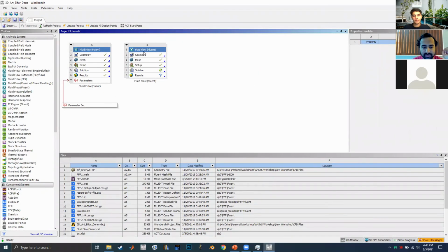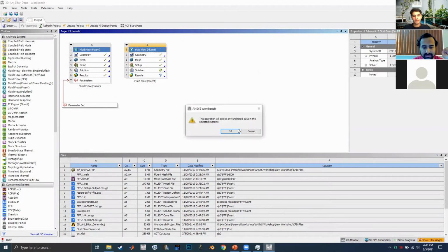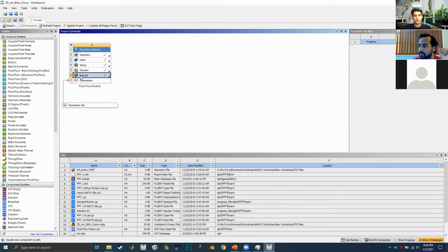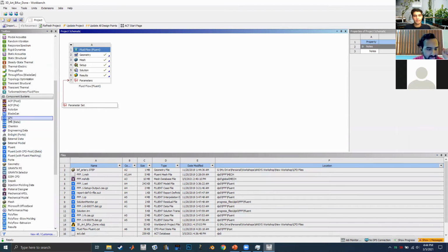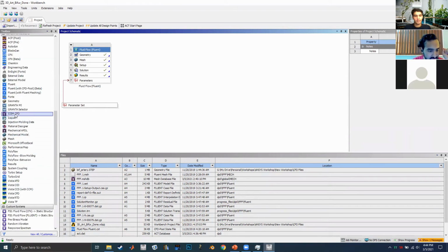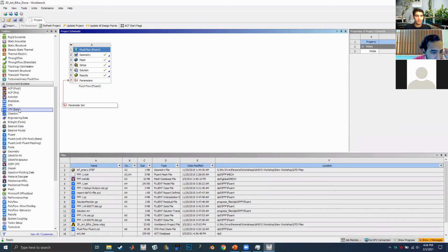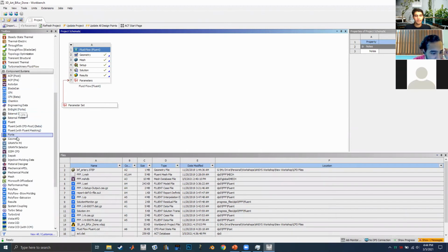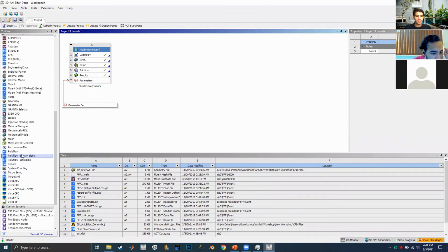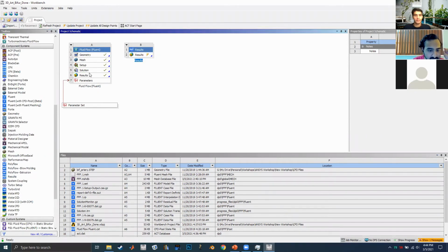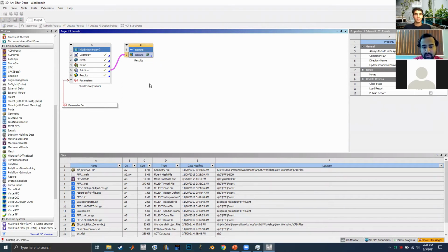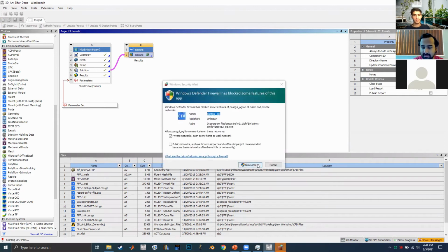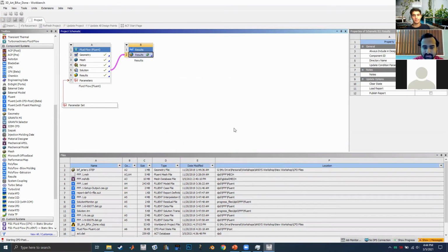So here's our simulation again. I'm going to go ahead and delete this. And then usually what happens is now you have your solution and you want to go to your results. So if I make a separate results thing, where is it? Fluid results. Grab this, transfer that there. This will open up what's called CFD Post, which is a special little environment that lets you process all your CFD results.